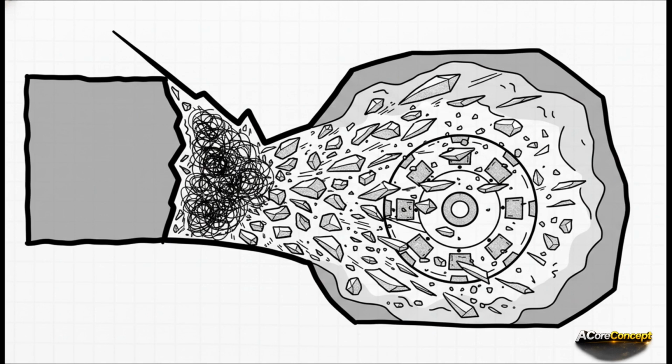During the Neelam Jhelum excavation, engineers realized that small, localized shear planes were actually acting like underground stress dams. They prevented the natural redistribution of stress, concentrating all that elastic energy until the rock literally erupted into the excavation workspace. It is an unpredictable and, sadly, incredibly fatal hazard.